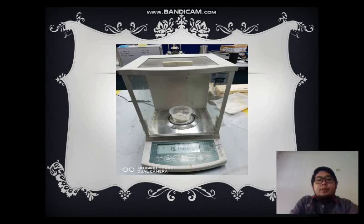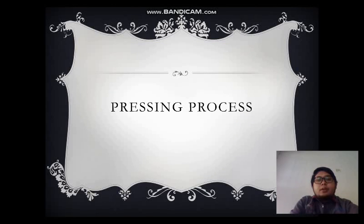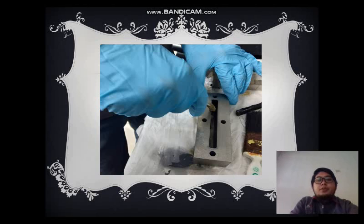The powder will be weighed using a weight balance. The powder is then sieved and then mixed with the bentonite, bauxite and kaolin. Next, for the pressing process. Firstly, make sure the mold is clean and remove all unnecessary objects or any contaminant to avoid failure of the sample.